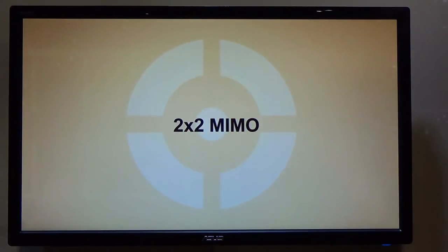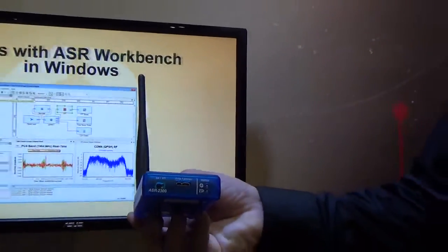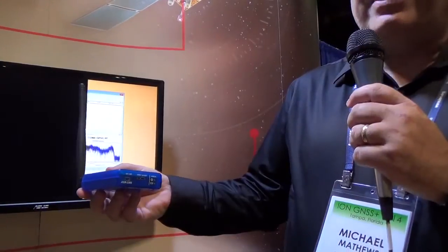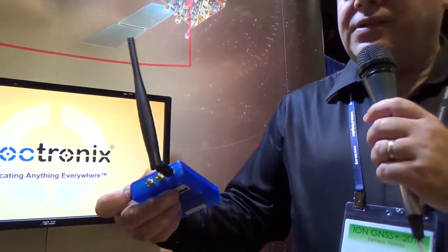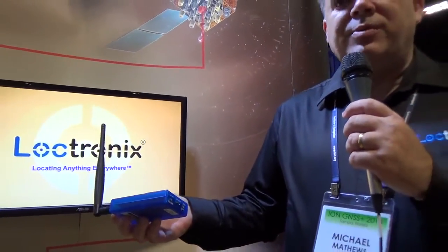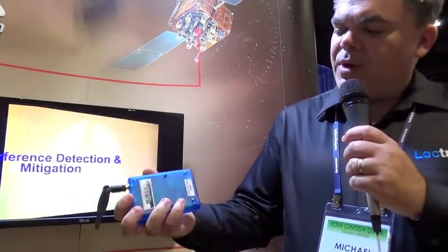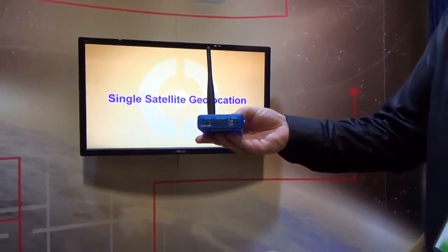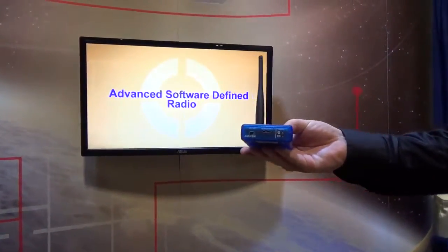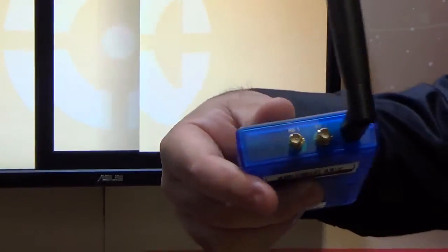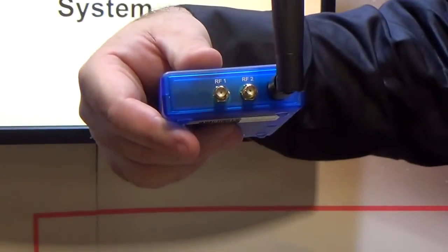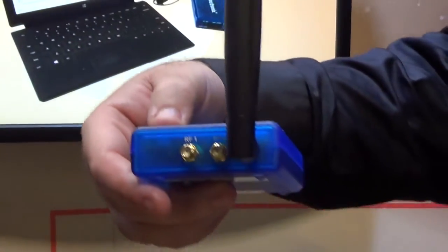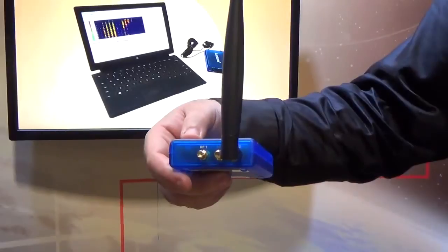The technology behind all this today is implemented on a software-defined radio platform and is available for embedded applications, as well as developing for laboratory and research implementations. So here's the box, and it runs with a USB interface for implementing easy connections, USB 3.0 to the host PC, and has a bunch of standard SMA interfaces on the backside that you can connect to the various RF inputs or outputs that are available to you on the device itself.